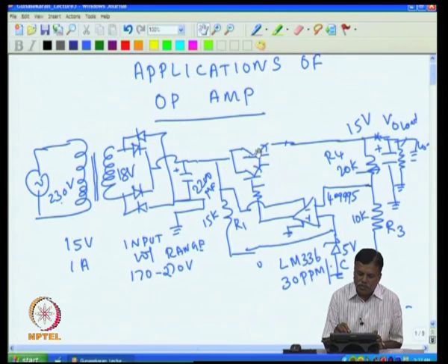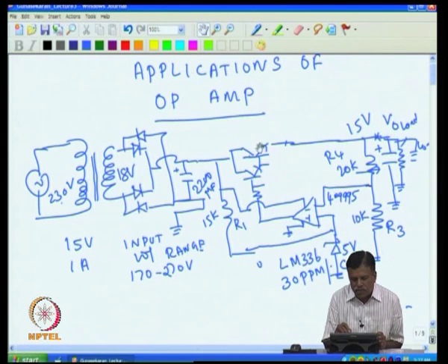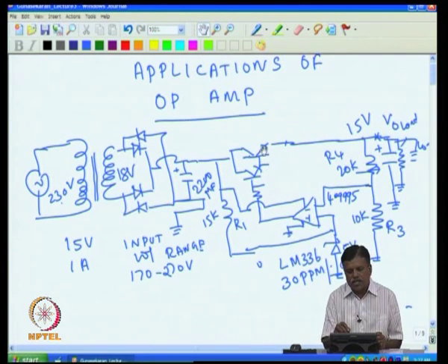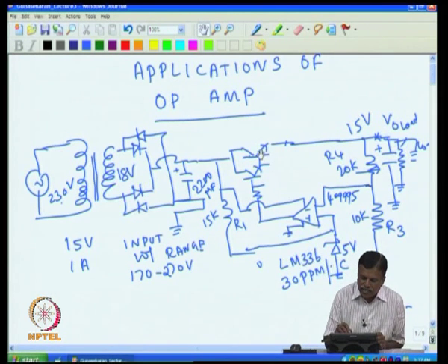So, if it is morning it went to 120 degree and come back to 20 degree, means thermal cycle 100 degree temperature change occurred, and the bonding wires inside expanded and contracted. So, for example, if I operate the transistor say at junction temperature 150 degree, so that is what maximum allowed, then you will find the transistor goes bad in about 200 to 300 thermal cycles.